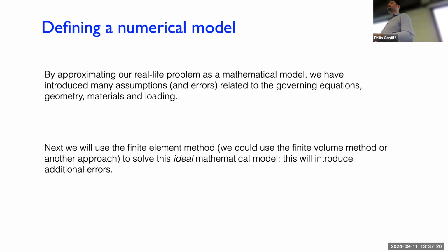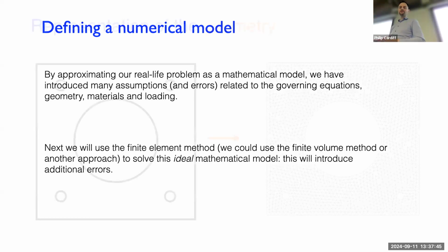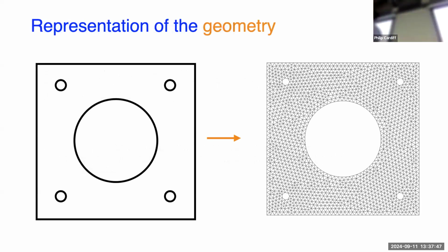So for example, if we make our mesh smaller, does that mean your model is going to give predictions closer to reality? Maybe, maybe not. All we can say is when you make the mesh smaller, numerical errors get smaller. That means your answer will get closer to the answer to the mathematical model. Whether that's close to reality or not depends on the assumptions you made in the model. So it's controlling these two different types of errors. That's the challenge for someone deciding things.